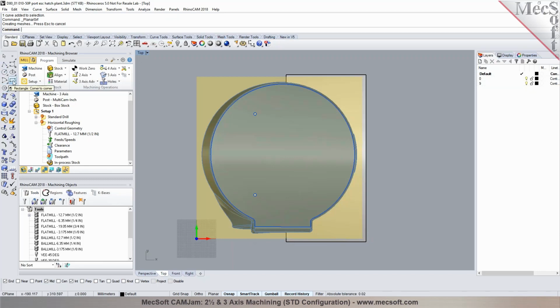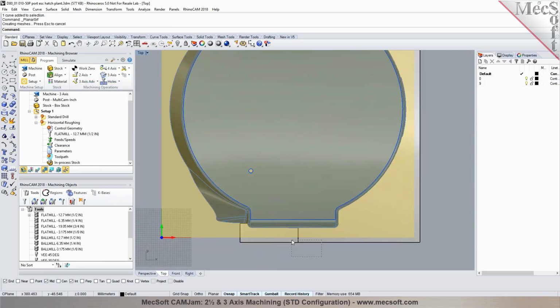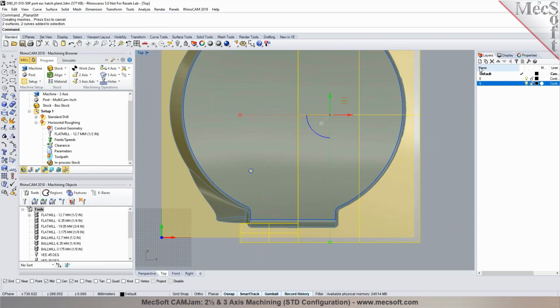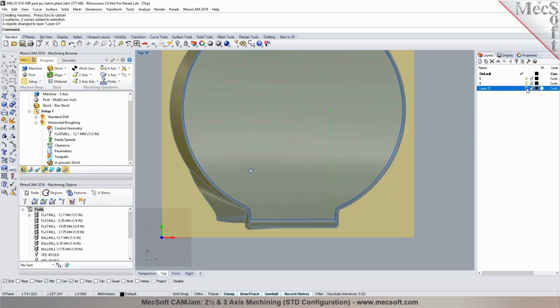Now, I could do a similar one over here too. I can use the same information and make a surface just extended from that whole underside and extend that whole surface so that it never cuts out. Absolutely. Cool. And I can have all of these in a new layer, and I can hide them when I don't need to have them visible. Right, exactly.